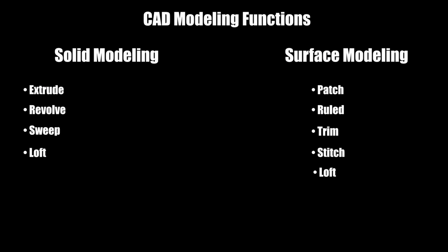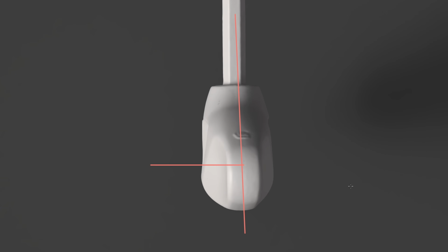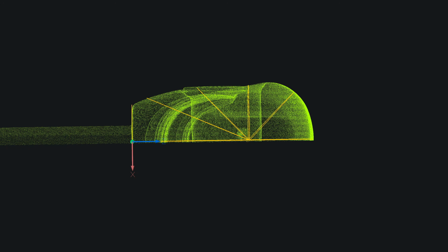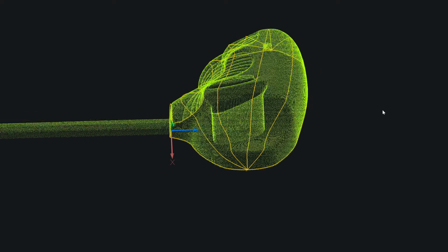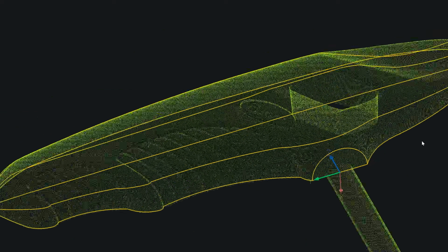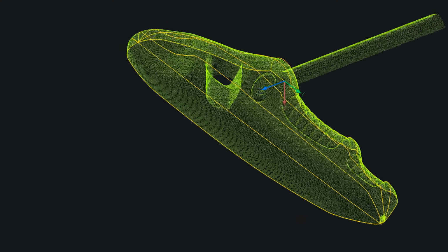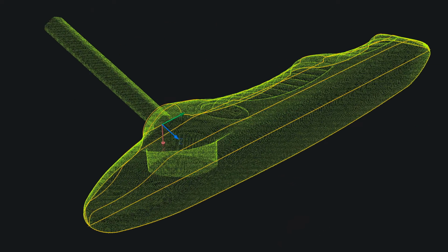In CAD, there are two main modeling approaches, solid modeling and surface modeling. You can work with either one or even combine both. For this tutorial though, I will be focusing mainly on surface modeling. In CAD, surfaces are built from sketch boundaries. Since 2D sketches are quicker to create, I will make 5 cross-sectional sketches spread along the longer axis of the handle. These sketches act as the main framework for 3D splines to connect to, forming across the boundary.